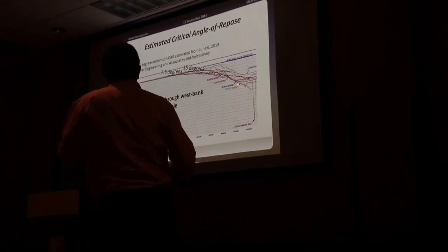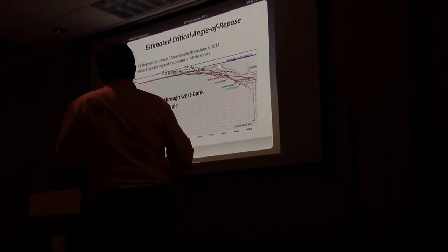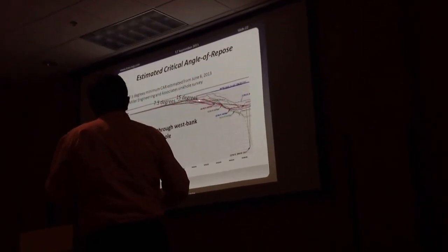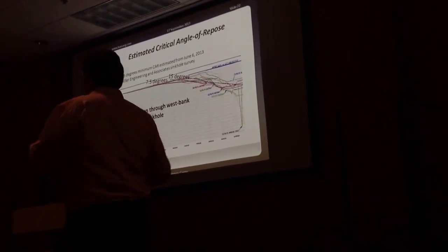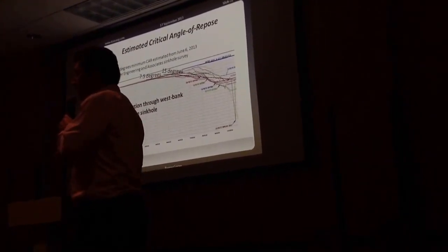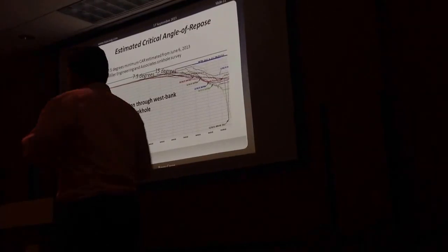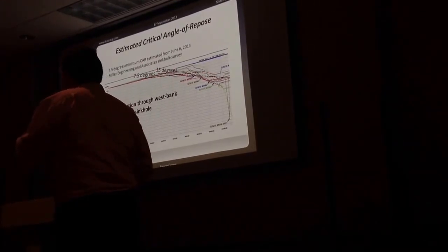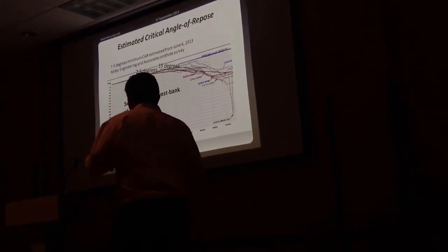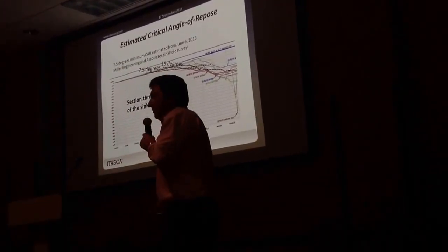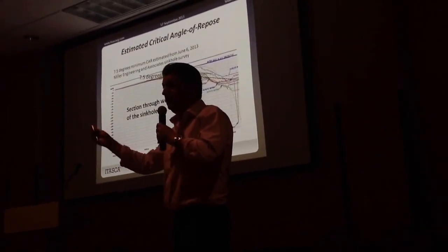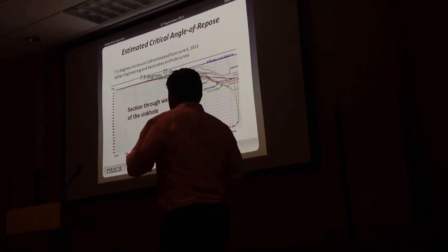And it is, within the sinkhole inner part, if you like. But the outer banks, because of the weak surface material, are taking on a much lower angle of repose, which means the sinkhole is broadening out. So it's down to 15 degrees in places and down to 7.5 degrees in other places. And this is something that we'll be watching through time because we want to understand what this angle of repose is going to eventually turn out to be.